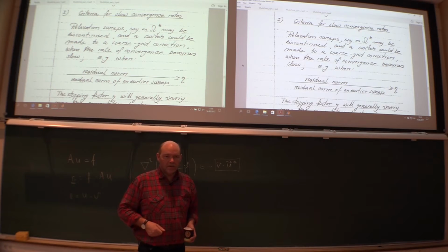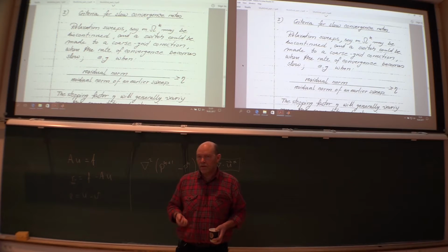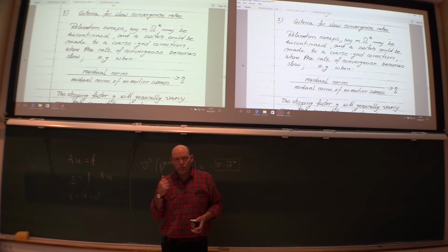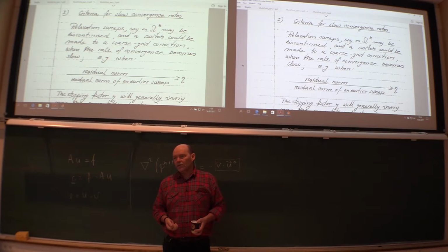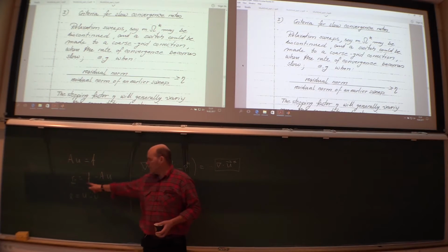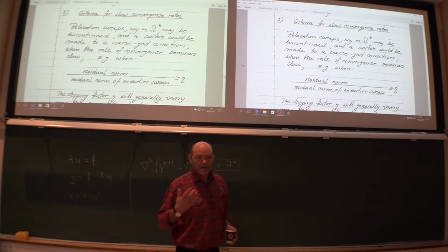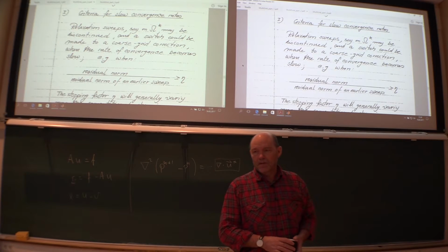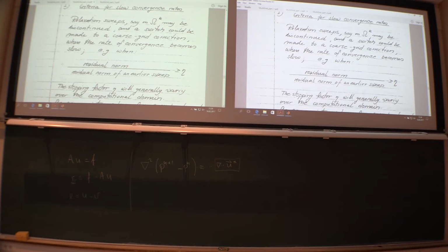But these amateurs programming Fluent in those days didn't think about what you normally start with for a case. You start with everything equal to 0. Then the first residual was 0, and then you divide by 0. The residual was 1 million or bigger and refused to become smaller. You couldn't get a solution at all. Very bad idea. Amateurs. I don't think they do it anymore.